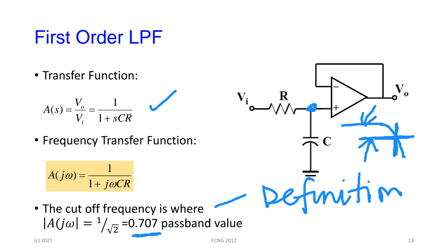It is known as a half power point, which is where the 1 over root 2 comes in. If you were dealing with power, it would be where the power in the particular signal drops to half. And since power is proportional to amplitude squared, the amplitude will be 1 over the square root of 2, right? You would have learned that from your circuits early on.